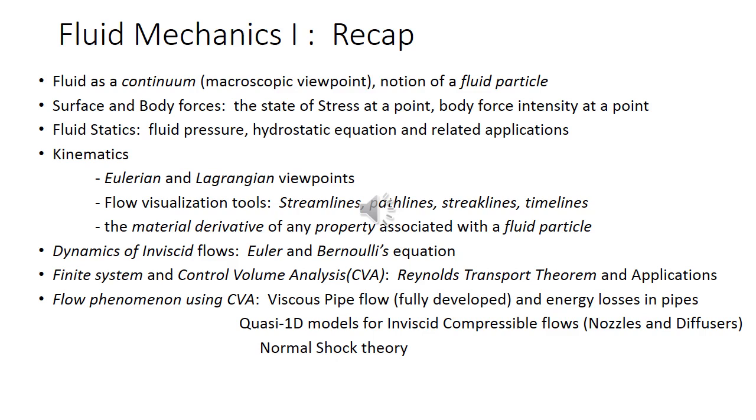Now moving on to surface and body forces. These are very fundamental force models for continuum fluid mechanics. What are these surface and body forces? Well, in a fluid, if you imagine any surface, then fluid on either side of the surface would be engaged in force interactions through the surface.